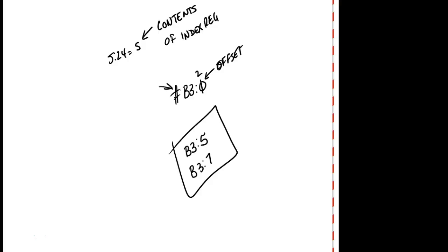The hashtag pretty much just tells you index register. So just looking at that, you have no idea what address it's going to use unless you know the contents of the index register. If you don't know the contents of the index register, it's not going to do you any good. So you say it holds the number, and when I put another number in, it changes, it adds it up. Is that what you're saying? What do you mean? You went from 5 to 7. Well, I changed my instruction. I changed the offset to 2.